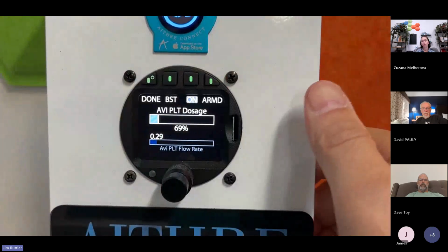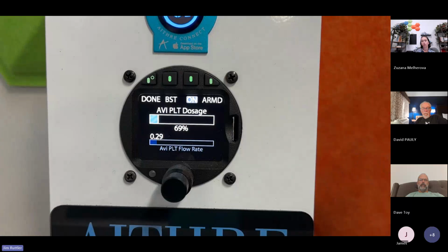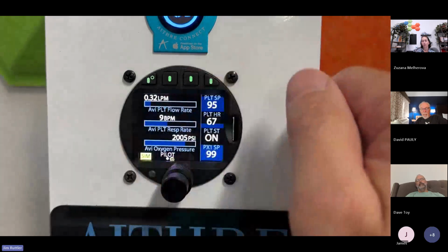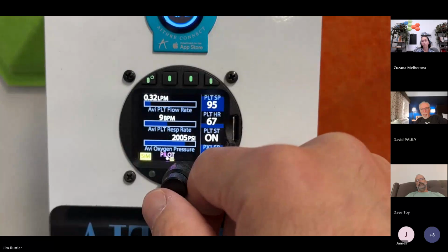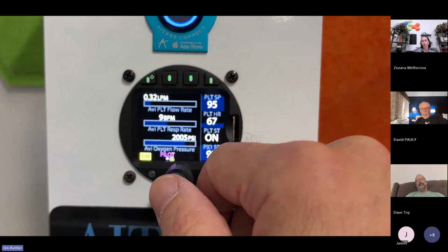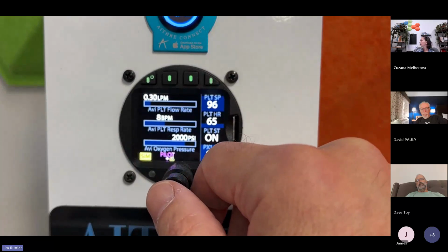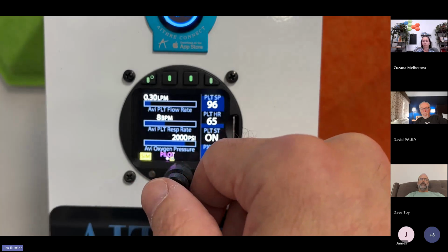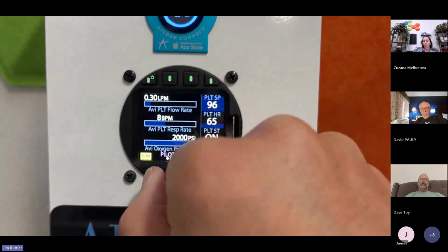If the ATD detects that your blood oxygen level is indicated here, then you can actually dial it back. So if you're acclimatized, you normally live in Colorado and you're flying at 12,000 feet, or you've got a passenger who's 18 years old, their blood oxygen level is often going to be very high, even at moderate altitudes, and you might not need to waste oxygen on them, so you could dial them back if you wanted to. If your blood oxygen level dips below, I forget the exact number, but off the top of my head, I think it's 85%, then it goes back up to 100% automatically, and it overrides that.